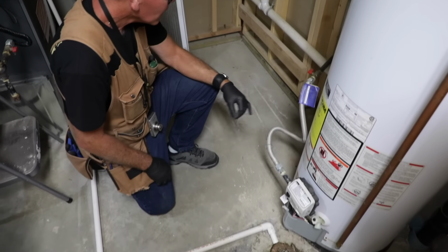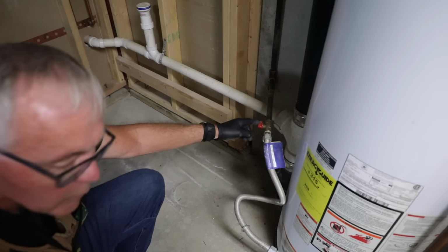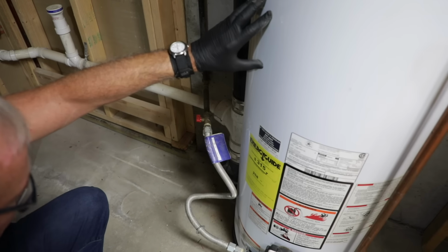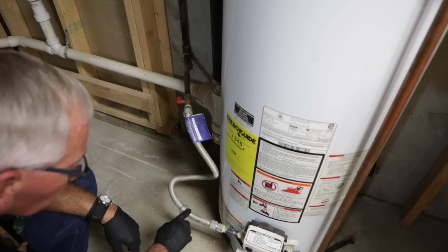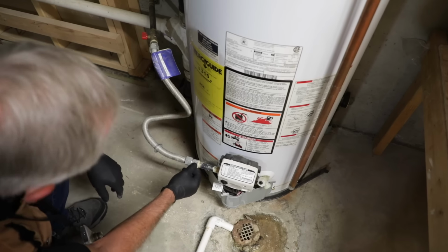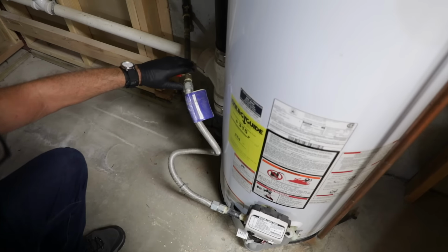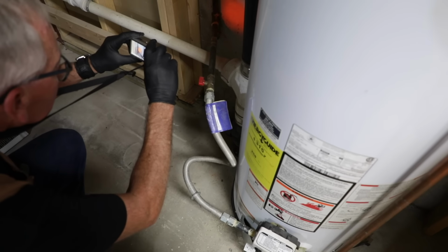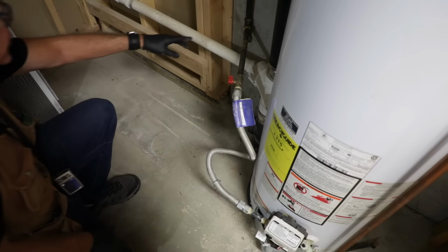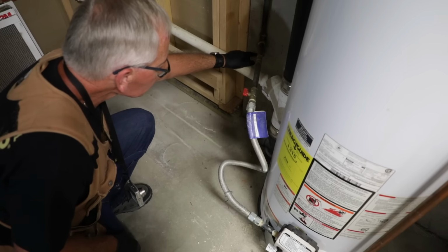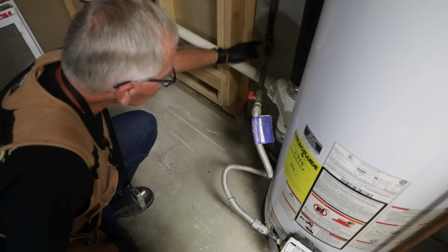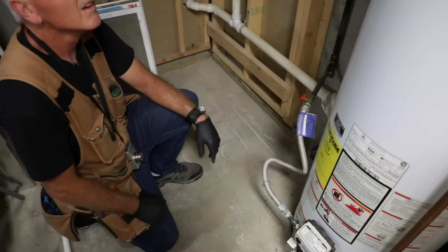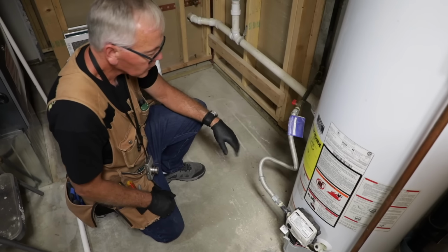Moving on down here, I'm going to check our fuel source. We're on natural gas here, and here's our shutoff valve for the water heater. So this is a natural gas water tank. Check our gas line, make sure it looks like everything's good there. I think that this is a little bit loose here. I think I'll recommend they secure this gas line a little bit better to the wall. You also want to make sure that you've got a trap down here on the bottom of the gas line, because this will allow any solids or debris that's in the gas to settle down below in this little trap. That's pretty important. So I think that pretty much wraps up our water heater inspection.